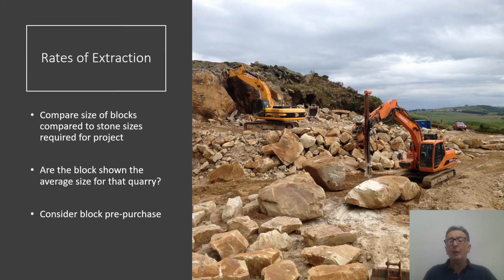A quarry visit will often give you an indication of the rates of extraction of material from that quarry, or at the very least, it will give you the opportunity to ask the quarry operator about their rates of extraction. It will allow you the opportunity to compare the different sizes of blocks that might be being produced, and as I've said previously, to compare those to the stone sizes required for the project.